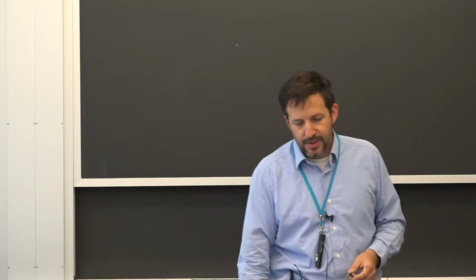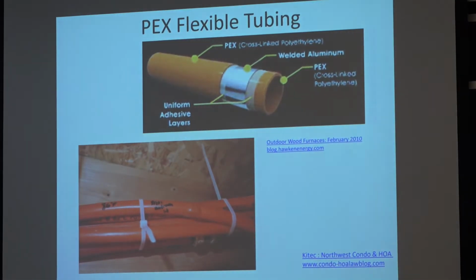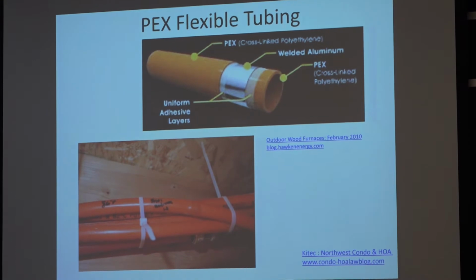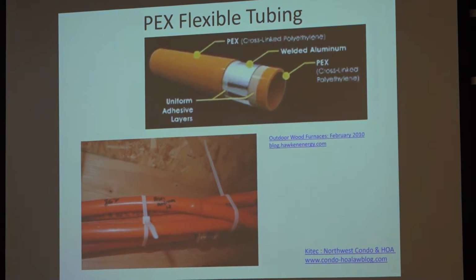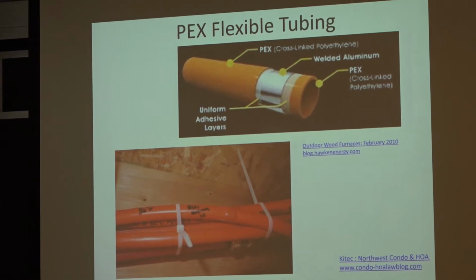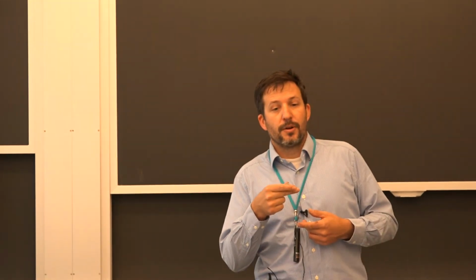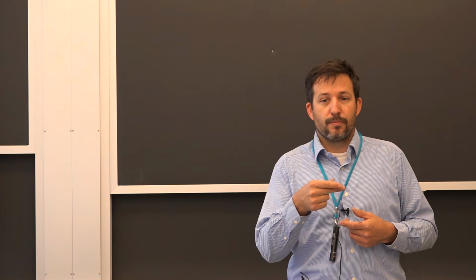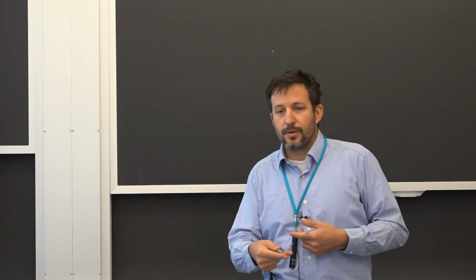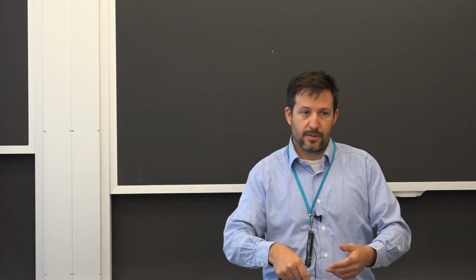Okay. There was a question after class last time about these examples of plastics or PEX tubing that had an aluminum foil. And sometimes it is because I skip a step. The reason for the aluminum foil, just so we're clear, is that they engineered it in there to stop the diffusion or transfer of oxygen from the ambient air into the piping system.